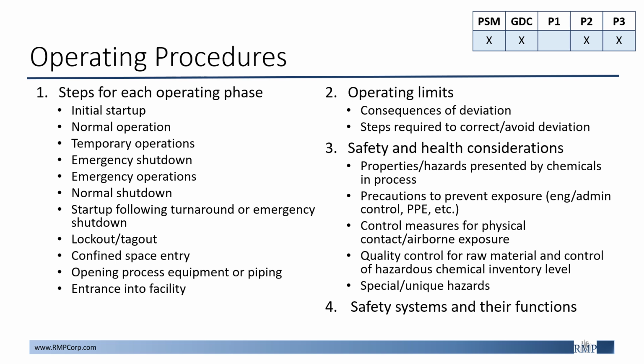Some potential issues inspectors would pick on include having a revision date that is more than a year from the date of inspection, realizing that operators are saying things that are different from what is written in the SOPs, and that management of change documents and the listed changes were not reflected in the SOPs. So these are things to be aware of.